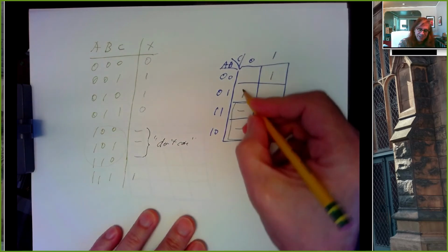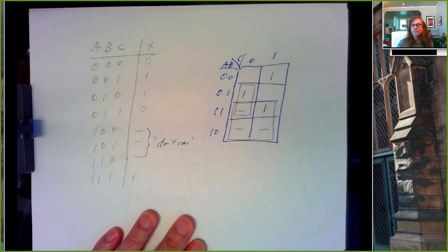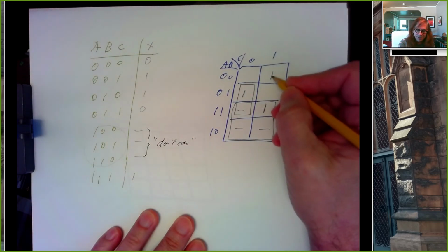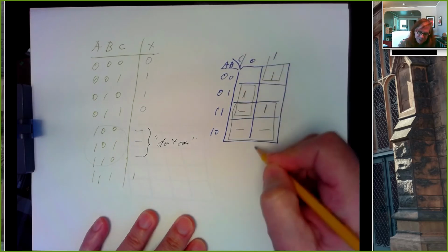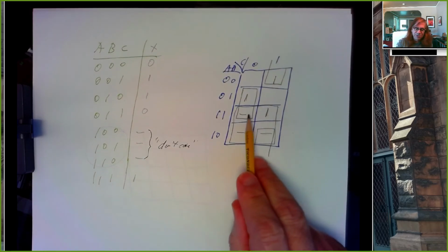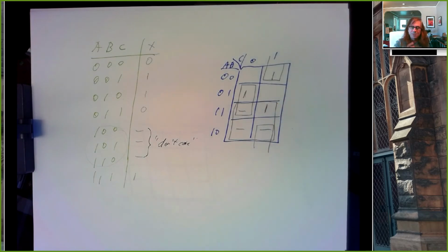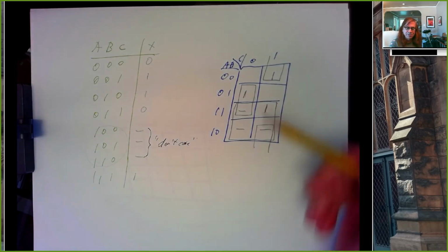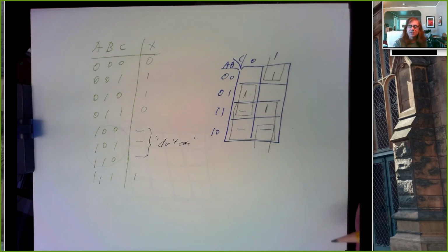And this dash, I can actually use that to cover this little isolated one with a better rectangle. And this one up here, I could cover with a broken rectangle like that. And that's a really nice cover, right? This 2x2 is going to eliminate 2 variables from my product term, and these 2x1s will eliminate 1, so I'll end up with a product term of 2 things, and then just a single term down here.